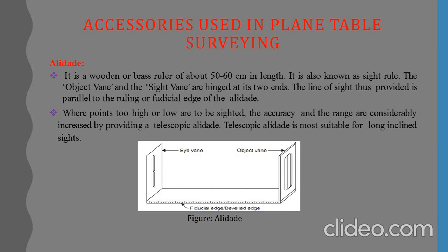Where the points are too high or low to be sighted, the accuracy and range are considerably increased by providing a telescopic alidade. A telescopic alidade is most suitable for long inclined sights.